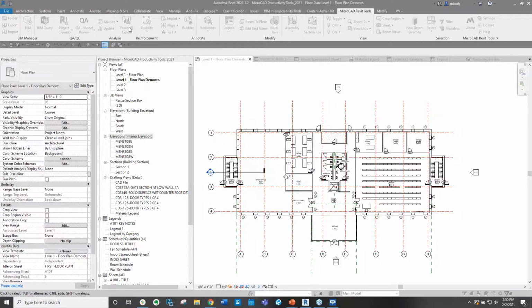That couch is kind of a good example. There's a couch in the Revit family that you can grab. And then when you place it in plan view, it will look correct. Or you can place it, and then you can link that to one of these Enscape couches so that it looks better in your visualization. The advantage of that workflow is not only do they display correctly in your drawings, but then they can also be scheduled.